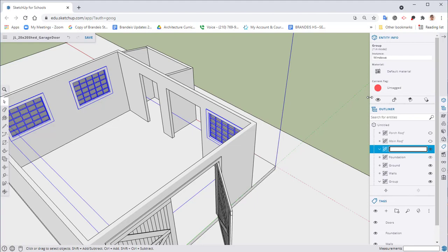All loose geometry should be untagged. If you start tagging loose geometry, it causes lots of problems. If you go in there and start hiding your tags with loose geometry, it really becomes a problem. So by default, all loose geometry is untagged, and this kind of reddish orange color.